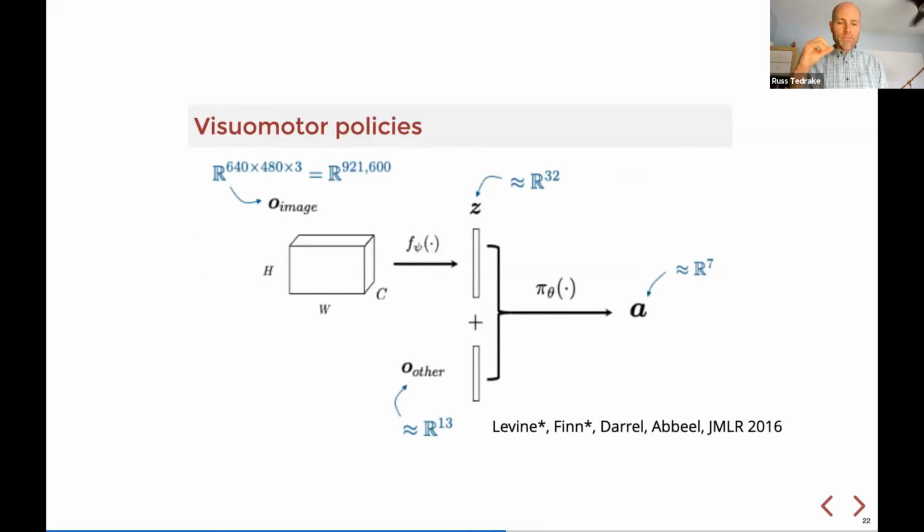They aren't stopping, planning, sensing, and then planning and then moving and making big mistakes. They're making very reactive motions based on the camera's input. And so we looked more carefully at how those systems were being architected. And there's a big feature that emerged, which is that people normally have a very big perception network, which is this O image going in that maps a relatively small set of features into the feature vector Z.